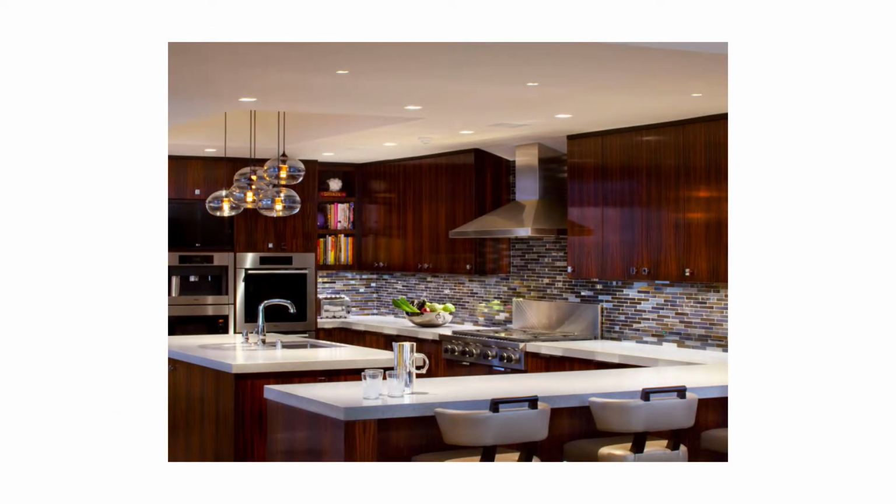Or even in a situation like this, choosing a square luminaire over those countertops with a very narrow light output, narrow angle for that light output, gets you really nice lighting on the countertop, not on people's heads, and it also creates a certain sense of visual hierarchy.